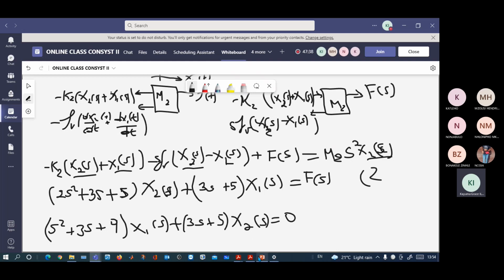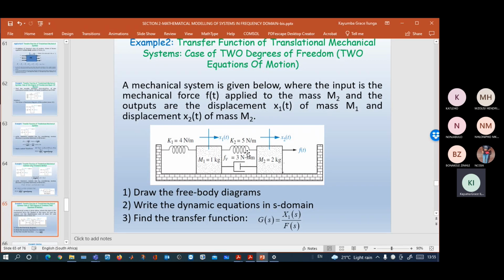let me show you here. When we are here, you see now. So multiplying this K2, K2 is positive. But when I take this force here, K2 times X1, it will become negative when I consider the motion. I say, okay, this has become a negative force because it's not going in the right direction. So you got it? Yes, I'm hearing you, sir. So it's not K2 that is negative. It's the force that is negative.